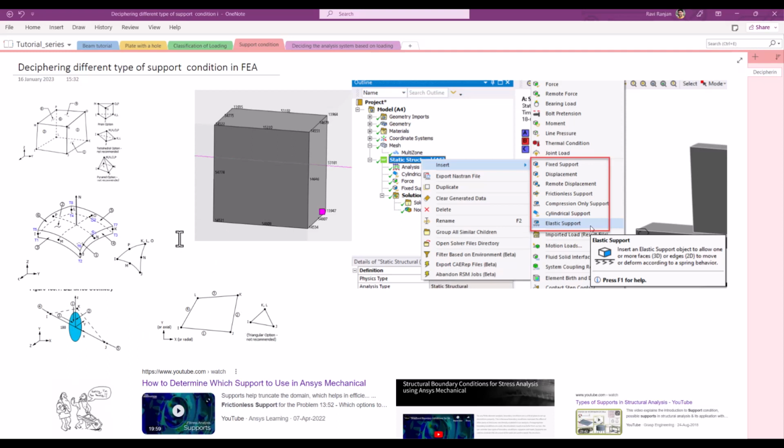At this point, it is worth highlighting that all of these elements don't have the same nature of degrees of freedom. For example, a single node of a shell element has 6 degrees of freedom: 3 rotation and 3 translation. But continuum-level elements like plane elements, used to model plane stress, plane strain, or axisymmetric simulation, or solid elements, which are volumetric, don't have any rotational degree of freedom associated with each node.